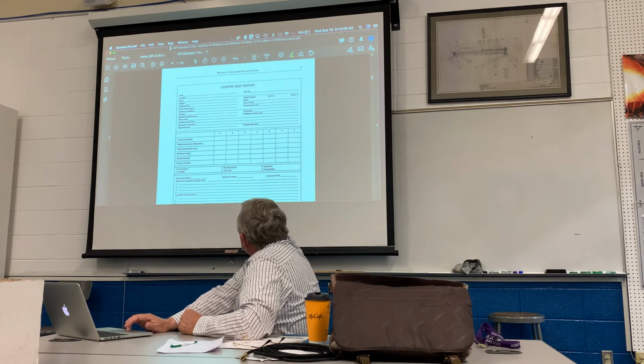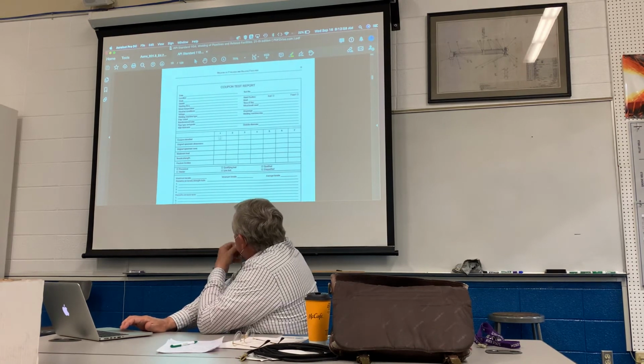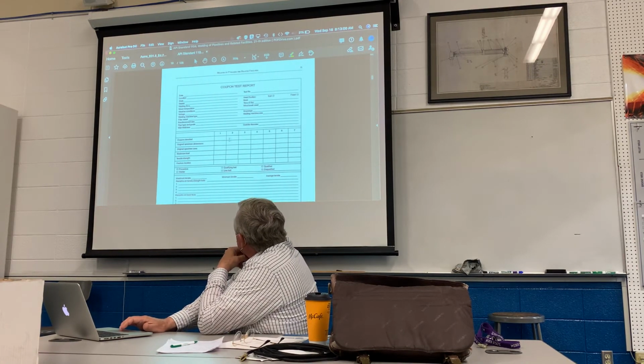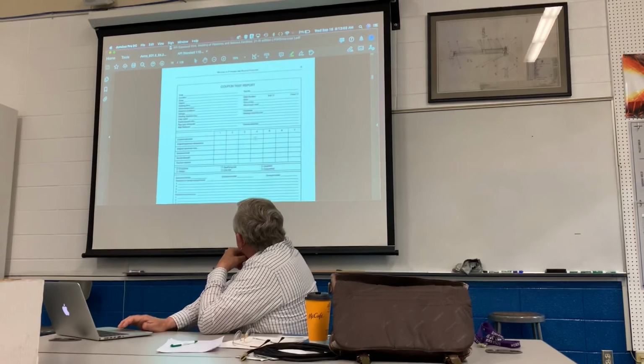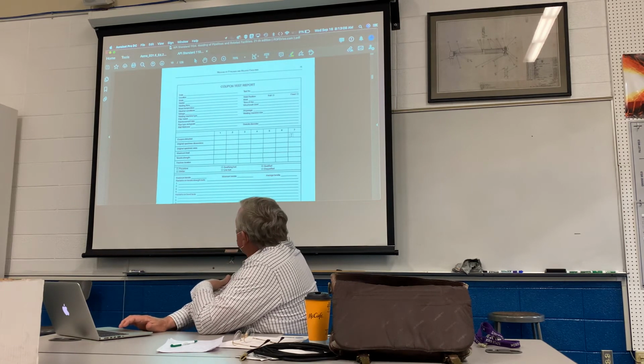Okay. In this little matrix right here, there are several different tests that can be pulled out of these, depending upon what test you're doing. This is going to be root 1, root 2, face 1, face 2, nick 1, nick 2, maybe a tensile or 2 tensiles or whatever is called out. And we're going to look at the chart in a minute.